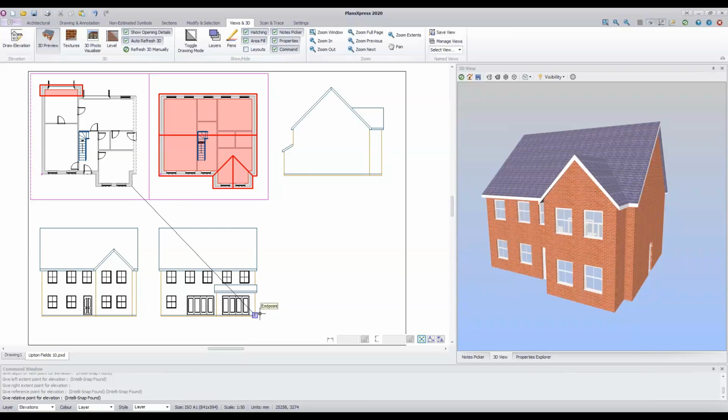Hover over these points again. Create all levels. Oh, there we go. Worked first time using the ground floor plan. So hopefully you're getting a feel for how you can draw those elevations and then how you can tweak them if there's any little bits that you want to adapt. And then you can do that by exploding the elevation first.